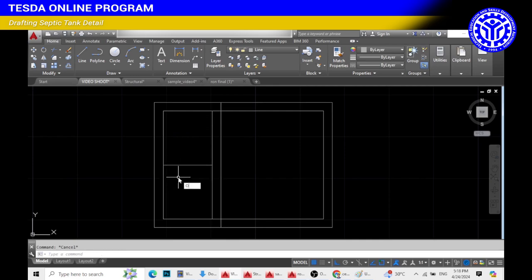Using the Offset command, offset the horizontal line by 0.05 meters, and drag the line downwards and upwards. Trim unnecessary lines using the Trim command.